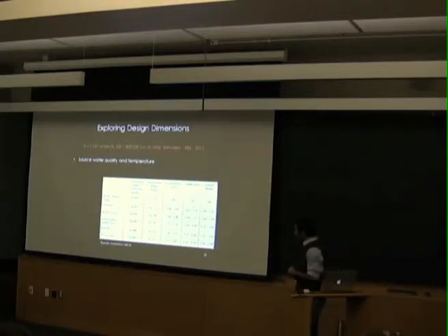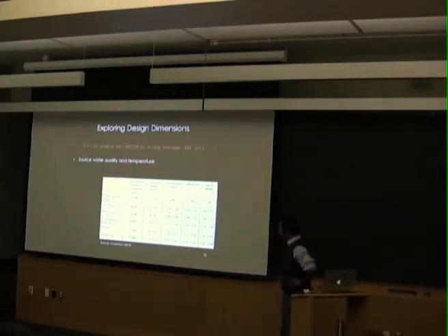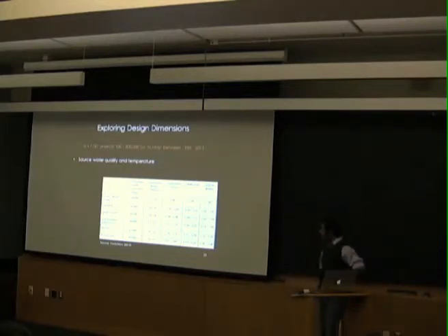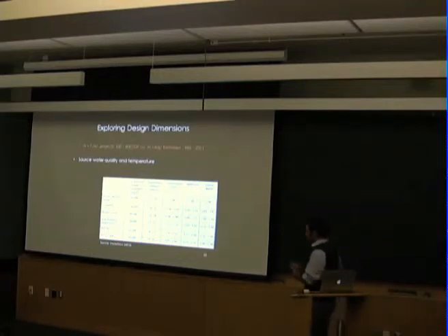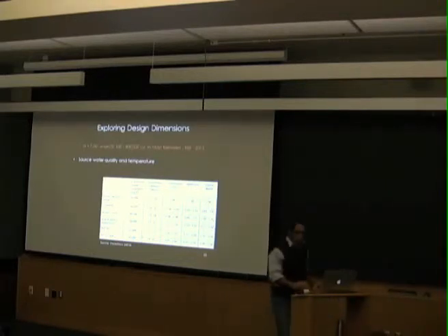Here's a chart that compares the TDS concentrations for the various oceans where you might want to install a desalination facility and some of the temperature ranges. Those are probably the two most important factors in terms of designing the facility. And typically you design it for worst case, so you would be very conservative and you would design for the top of the range.